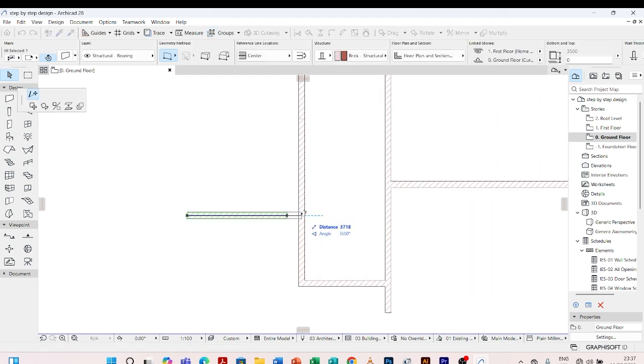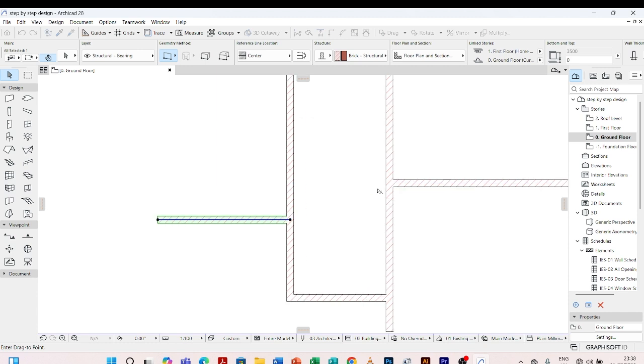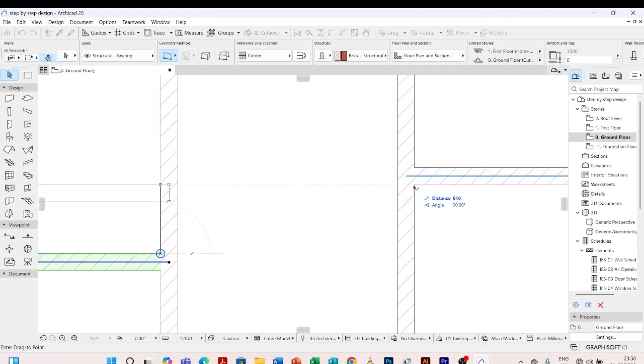So I want this wall, from this wall I want it to be at 1.2 meters. So I Ctrl D, that is, sorry, dragging it. Then when I'm to move it, I hold on shift to get the exact point. I put it at this.